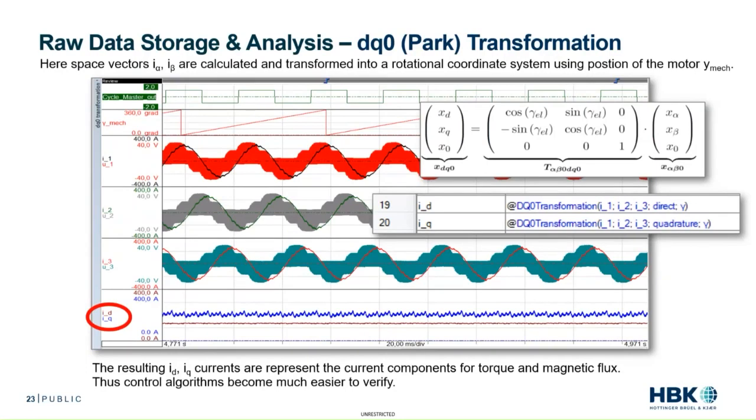So now the motor can easily be understood, and actually inverters think in DQ0 entities, since this is what they compute, and basically this allows you to compare the calculated DQ0 control measurements from the power analyzer, which can then be streamed to your dyno, and compared to your inverter's DQ0 control measurements. So this helps engineers like you develop inverter firmware and understand how well the inverter works with the motor, and maybe decide you'll need to change the firmware to achieve better results to improve the efficiency, especially during control changes.